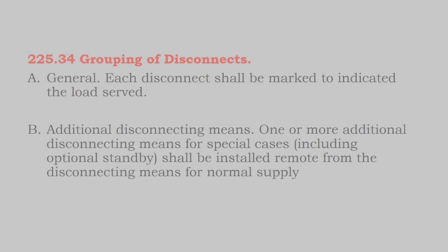But if you're designing an emergency backup system where there are critical loads that must remain energized, even when the fire department is trying to purposefully power down the building, those switches need to be separate from the normal power supply to indicate to the fire department that they're there.